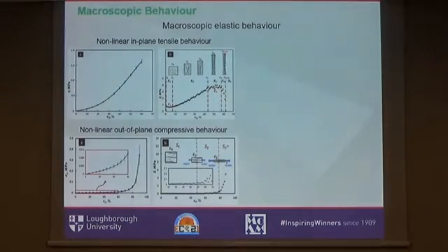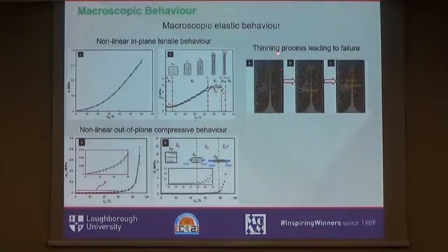And here you can see the specimen, which is in the grips, and these spheroids are nothing else than bubbles in the water. We can't remove them, obviously, so you should concentrate only here. What you can see is a significant level of extension, and then the material starts localizing its deformation, thinning, and then finally there is onset of the crack and its propagation.